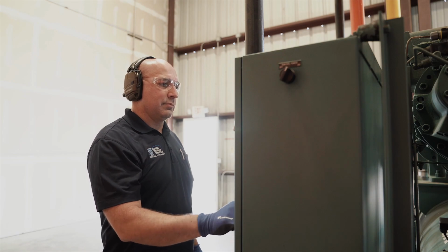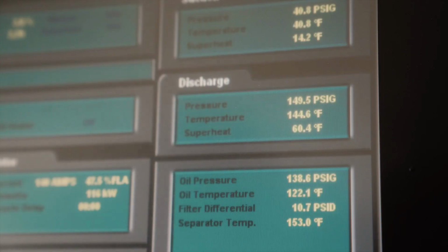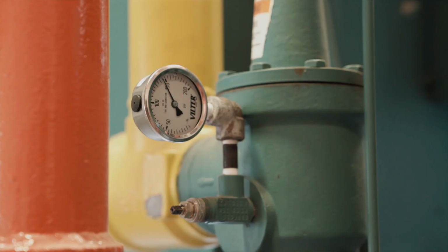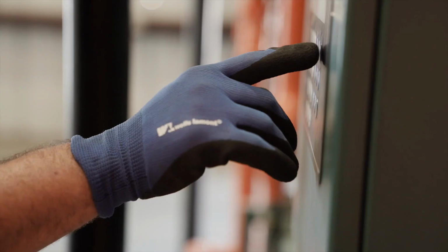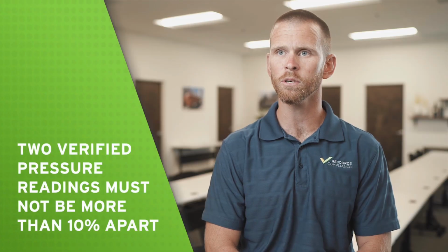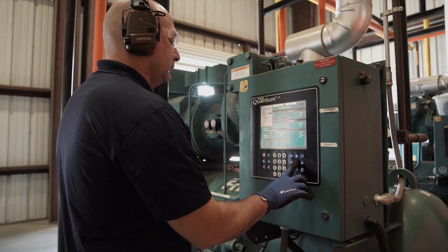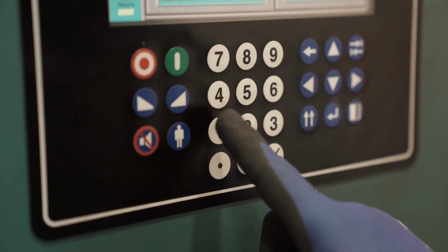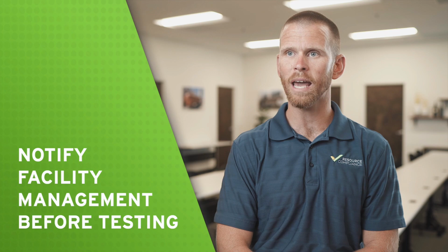Keep in mind that to use this method, one must first verify that the pressure transducer reading is accurate. This can be achieved by installing a trusted gauge to ensure both the gauge and the transducer read substantially the same pressure. IIAR Standard 6 recommends that the transducer be verified at two pressures that are 10% or more apart. A successful test will de-energize the compressor, so it is important that trained personnel be available to restart the equipment after completing the test. Before testing a high-pressure cutout, make sure to notify facility management that the test will be